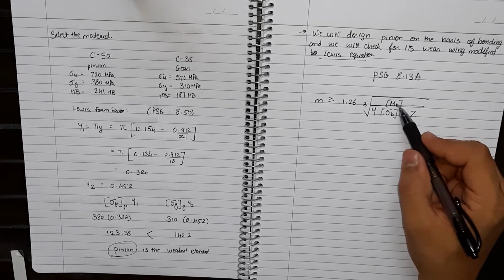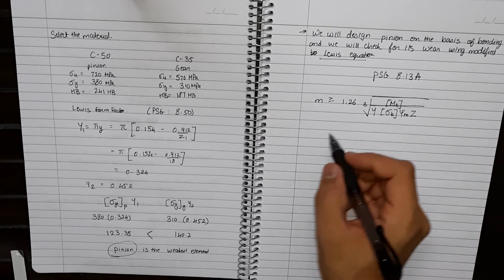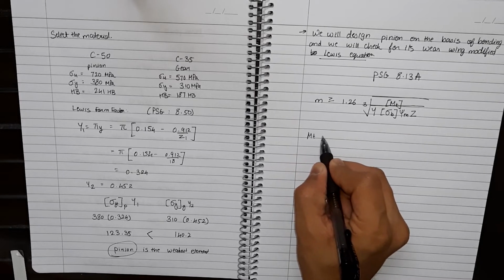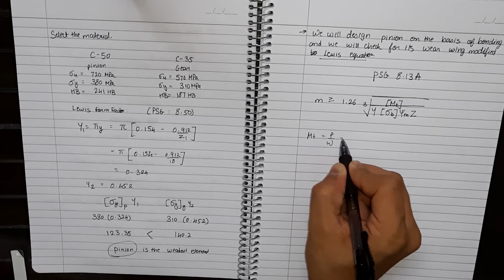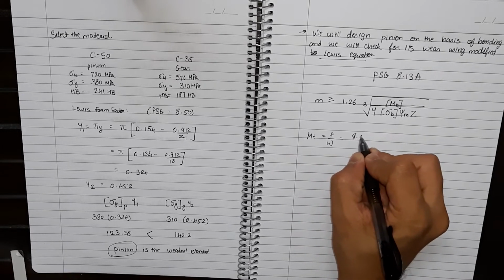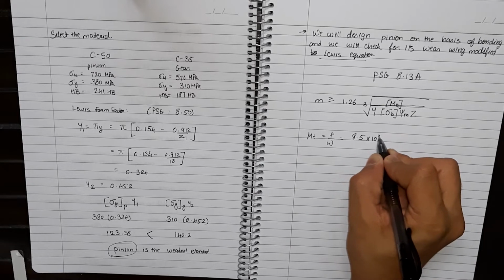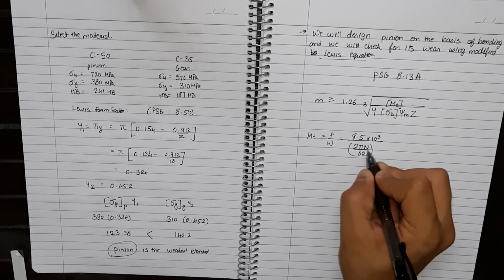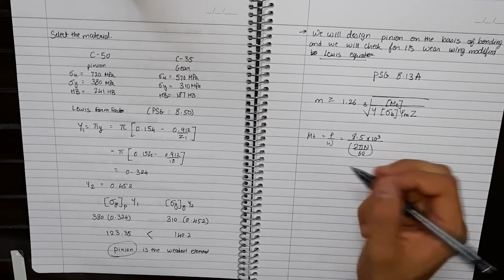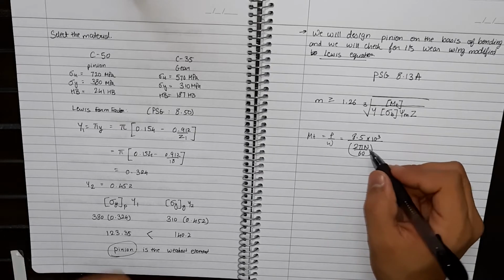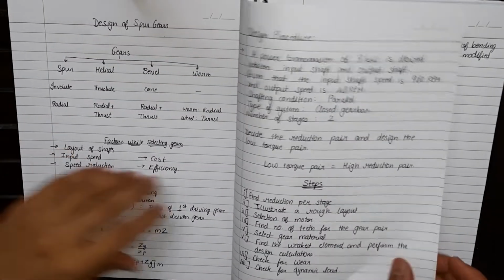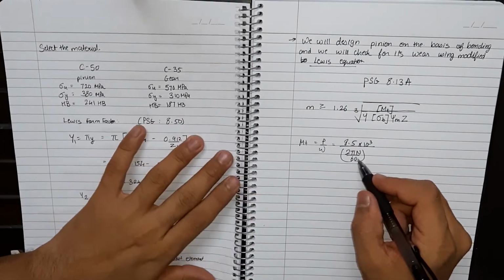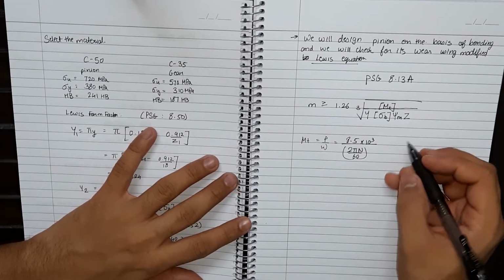So let us start with the design torque. Now how do you find the design torque? We have this formula that torque equal to power upon omega. So let's say that this Mt is equal to P upon omega. Now the power that we had selected was 8.5 kilowatts. So it is 8.5 into 10 raised to 3. And omega is 2 pi n divided by 60. This is revolutions per minute and this is radians per second. So when we substitute the value of n, what is the value of n? The value of n is 960 rpm. So you substitute the value 960 rpm here, and what you get is